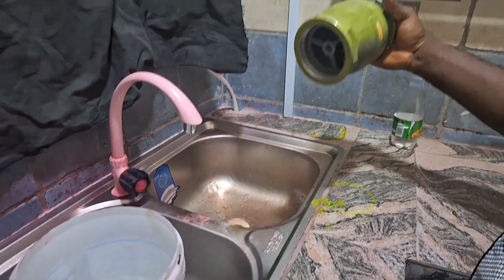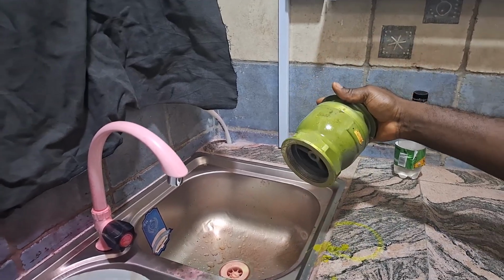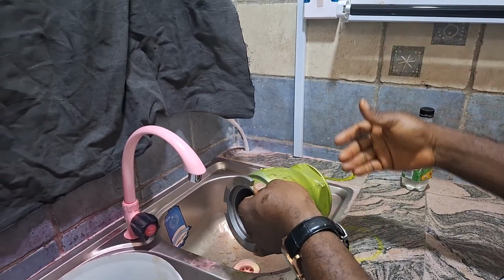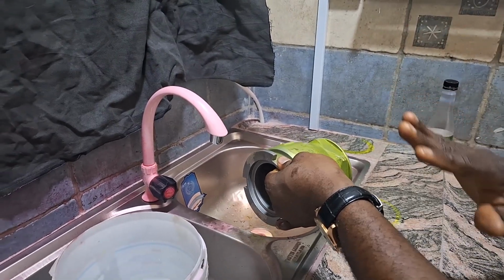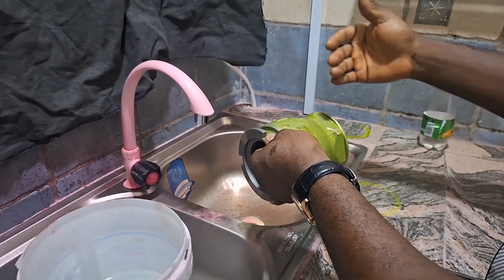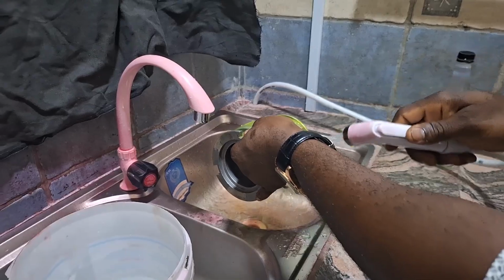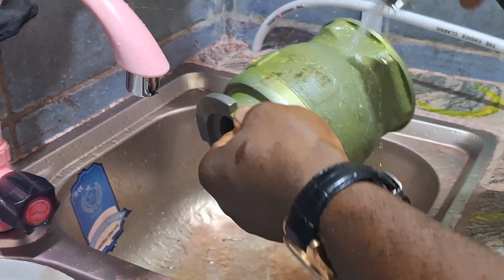So after applying your penetrant and allowing it to dwell for your usual dwell time, for hydrophilic, you need to do what we call pre-rinsing. For lipophilic, you do not do pre-rinsing. When you do pre-rinsing, you just use water, you put water on it to first of all remove excess penetrants.